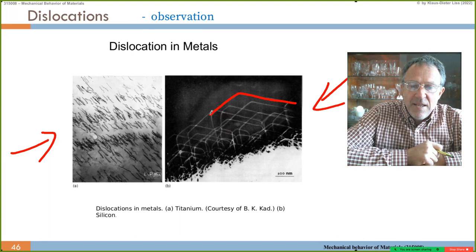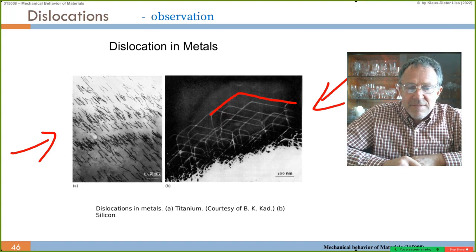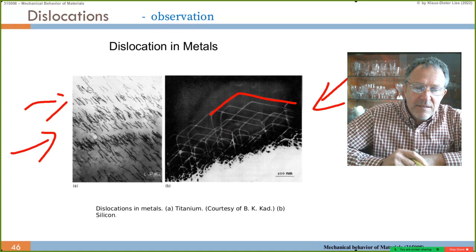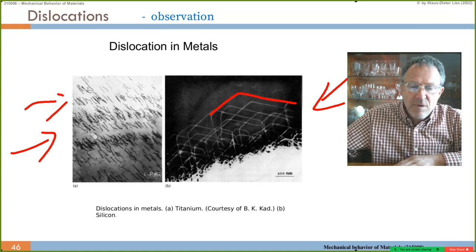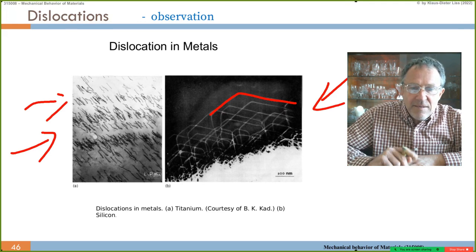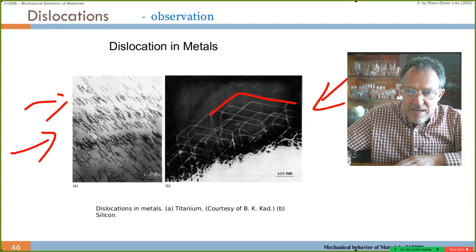So we can see they have relatively sharp corners because the bending may widen the dislocation width in the bend, which is not favorable for the covalent bond. So we get more the lattice oriented directions, while in titanium and metals, soft metals, they can be more zigzag, so more arbitrary orientations. And this is also when you have a wider dislocation width, then it can jump from one to the neighbor location.